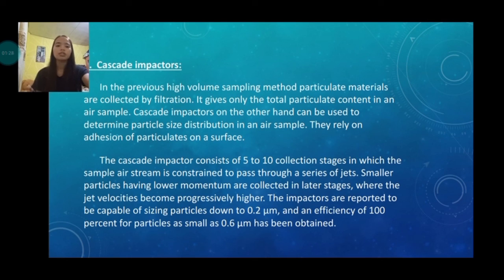The impactors are reported to be capable of sizing particles down to 0.2 micrometer, and an efficiency of 100% for particles as small as 0.6 micrometer has been obtained.